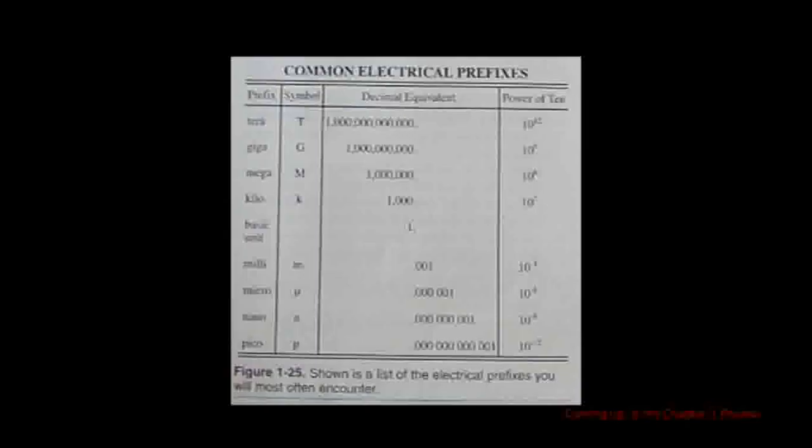When an electrical quantity, such as a voltage, is written, it is expressed in units such as kilovolt, megavolt, millivolt, microvolt, to avoid using an awkward numerical form. For example, the quantity 5 million volts would be written as 5 MV. If the quantity was 0.005, or 5 thousandths of a volt, it would be written as 5 mV, with a small m and capital V. It is important to note the use of the uppercase letters and lowercase letters in these units. When voltage is expressed with a capital letter M, it represents millions of volts, but when the voltage is expressed using a lowercase m, it represents the fractional units of thousandths.